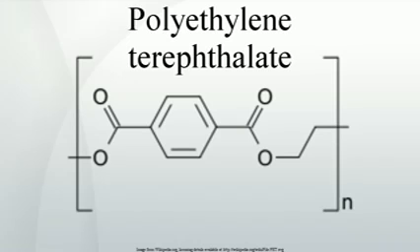Another common modifier is isophthalic acid, replacing some of the 1,4-para-linked terephthalate units. The 1,2- or 1,3-meta linkage produces an angle in the chain, which also disturbs crystallinity. Such copolymers are advantageous for certain molding applications, such as thermoforming, which is used for example to make tray or blister packaging from co-PET film, or amorphous PET sheet, APET, or PETG sheet.